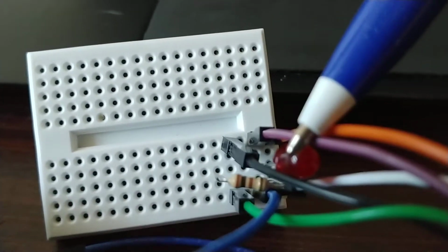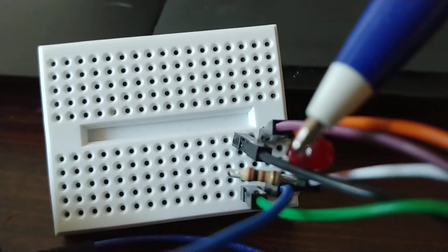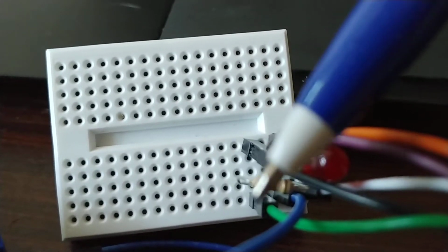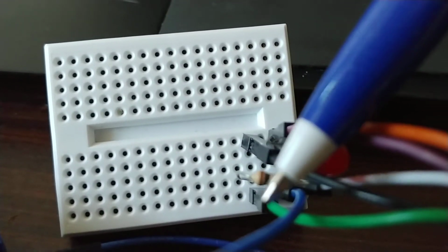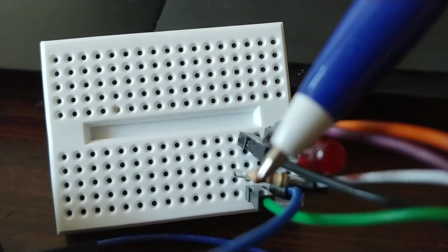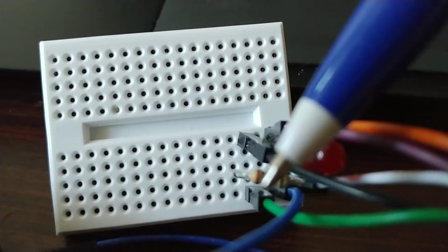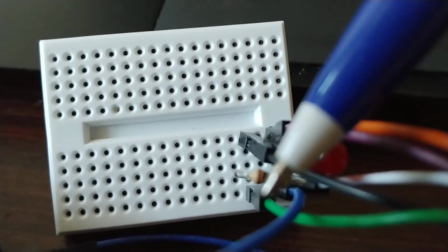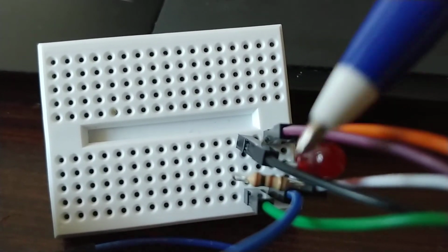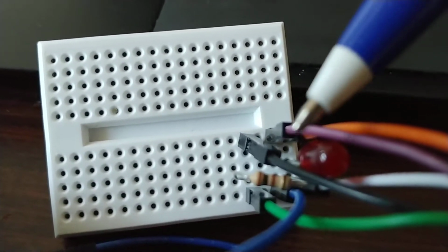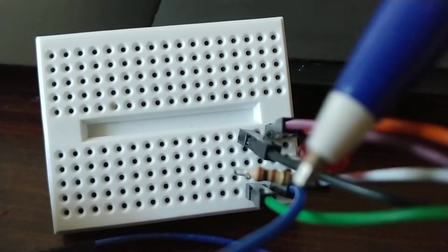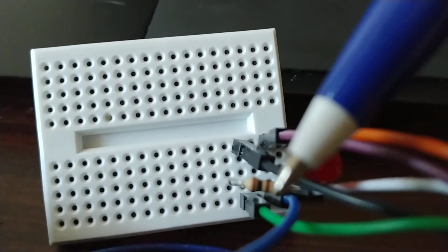Now down here is our abridged proto board. We have an LED connected in series with a 100 ohm resistor, and it might look like it's into that hole, but really everything is along that hole. That's the ground of the M2K, and that is V2 minus. Channel 2 is measured across the resistor, channel 1 is measured across the LED. This will be our LED voltage, and this voltage divided by 100 ohms will give us the current.